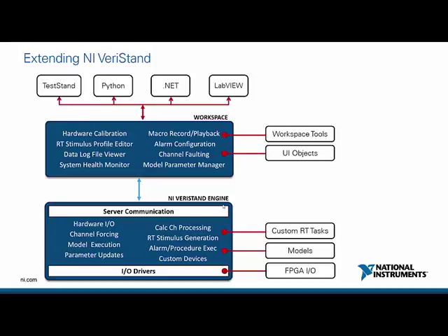And then the things along the top, these are ways that you can automate VeriStand, or ways to plug VeriStand into higher-level application software. So nearly everything in VeriStand has a .NET-based API to go with it. So if you wanted to use TestStand as your high-level automation software and just call VeriStand in the background, the .NET APIs enable you to do that. That's a pretty common thing that we do today, and a lot of our customers do that.